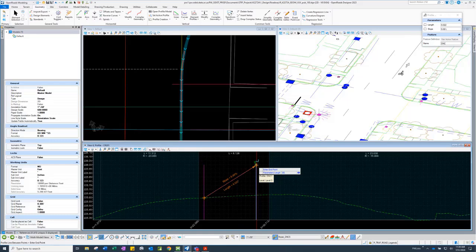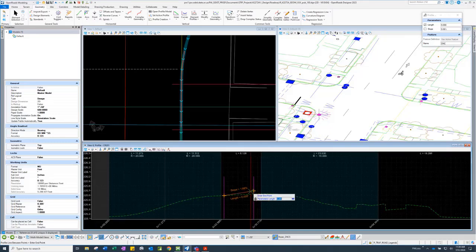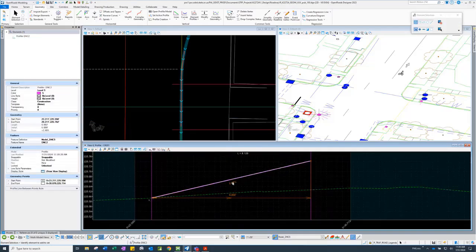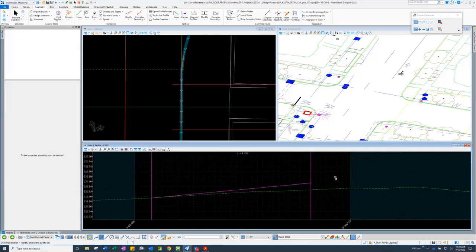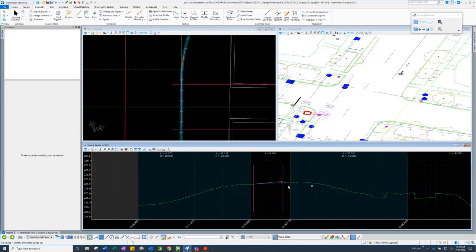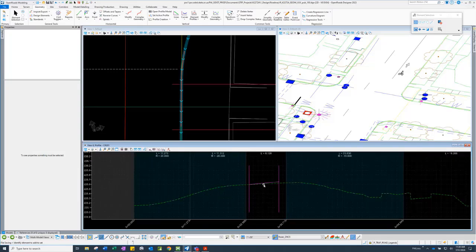So I'm going to say 6 feet. I'm going to tab over. So now it's giving me 6 feet. I'm just going to randomly select a slope, accept it basically. And I now have a line that I can actually manipulate the rules to 1.5%. Ooh, I'm flat. I need to go flatter, right? You now have the ability to adjust based on the existing conditions. So this is my control line to make sure my ramp is compliant. So looking at this, I would be like, okay, so I just need to maybe match existing.